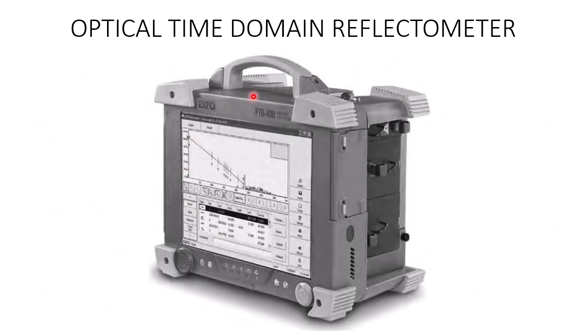This is an example of an optical time domain reflectometer. Just the picture is shown, but we have to connect the optical fiber and start the machine, and everything will be done inside. All of the components that were shown in the optical fiber backscatter reflectometry setup are present right here, and the chart that we saw in our previous slide is available on the screen of this particular measuring instrument. From that we can easily determine what type of fault is present in the fiber.